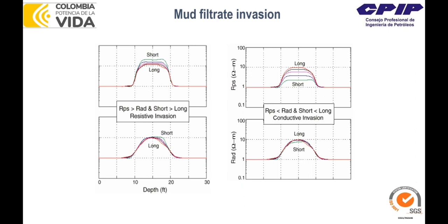But in the case of LWD, this problem is not that severe because of one parameter, the so-called time after bit, which is not that big. For example, if you drill with normal ROP, right, the mud doesn't have much time to invade the formation. So this effect is really not so obvious. But if you are working with wireline tools, when you log the well like one day after it was drilled, or like 48 hours after it was drilled, the effect is obvious. Okay, so you will always see the effect of the invaded formation.